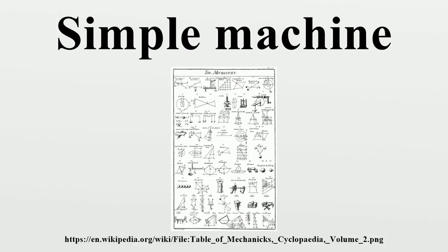In an inclined plane, a load can be pulled up the plane by a sideways input force. But if the plane is not too steep and there is enough friction between load and plane, when the input force is removed, the load will remain motionless and will not slide down the plane, regardless of its weight. A wedge can be driven into a block of wood by force on the end, such as from hitting it with a sledgehammer, forcing the sides apart. But no amount of compression force from the wood walls will cause it to pop back out of the block.